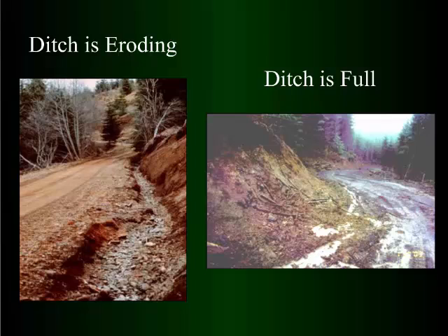No functional ditch here. It looks like probably a skidder or something's ran back in here. It's ponded out in the road. Subgrade is saturated. You're going to get subgrade deflection. Basically, this is probably an active timber sale. I'm guessing they'll probably come in and clean it up, but they need to maintain that during the timber sale, or they're in danger of actually losing their road or the use of their road through here.